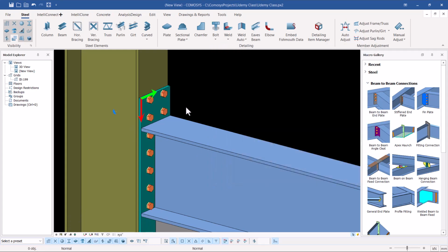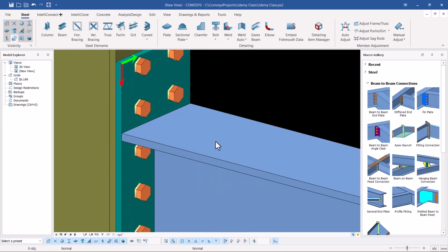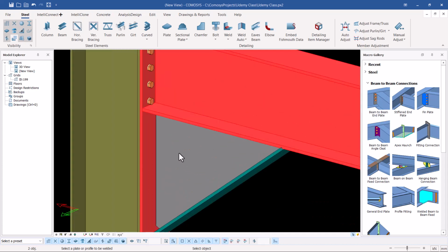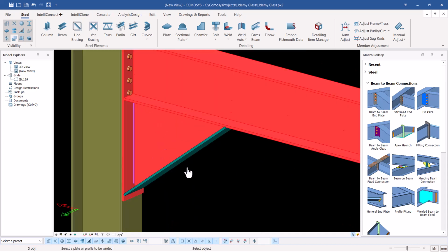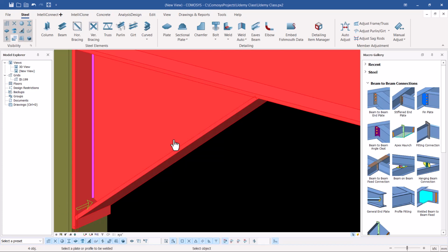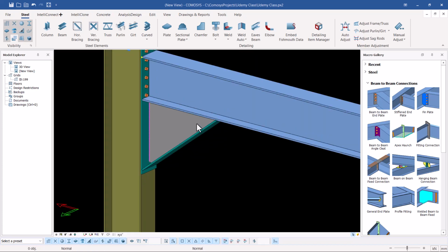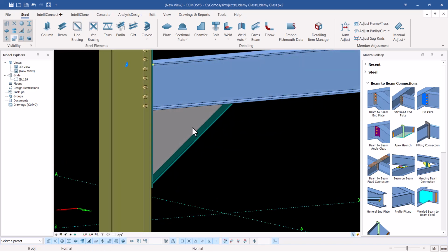So I've just shown you how to create a bolt here, and maybe you want to weld this to that member. You can always come to auto weld, pick on auto weld and pick 2 components. I want to weld this to that, and I've created a weld, and I want to weld this to that, and I've created a weld, and I want to weld that to that. So to confirm the assembly, I've not welded that. Let me just go back and create a weld between that and that.